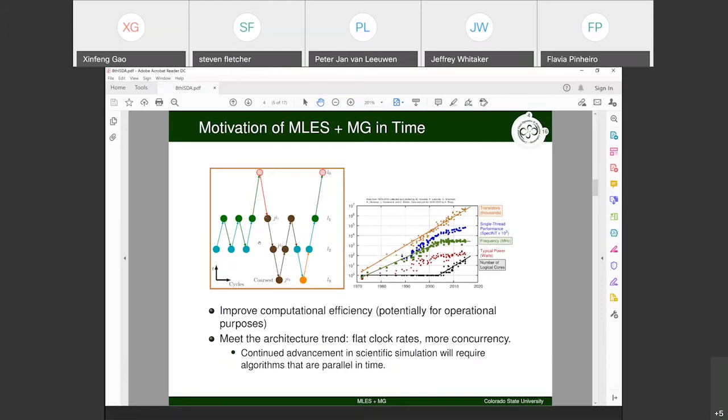So this is a multigrid, a relatively full multigrid. Ideally it will start at the coarse level, and then we prolong to the finer level: coarse level, then medium, fine, finest. We want to start from the coarse level, but sometimes, if you have more computational power, you start from a relatively decent mesh size and then smooth your problem a little bit. That's good too.